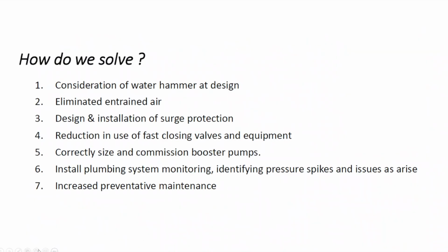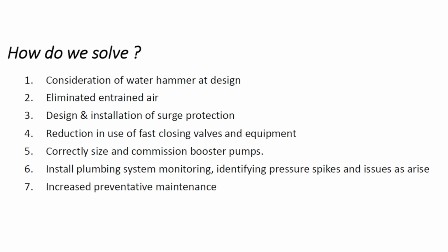His takeaway message, how do we solve it? Consider water hammer at design, eliminate entrained air, design and installation of surge protection, reduction in use of fast closing valves and equipment, correctly size and commission booster pumps, install plumbing system monitoring, identifying pressure spikes and issues as they arise, and increase preventive maintenance. So it is an ongoing issue that we need to address.